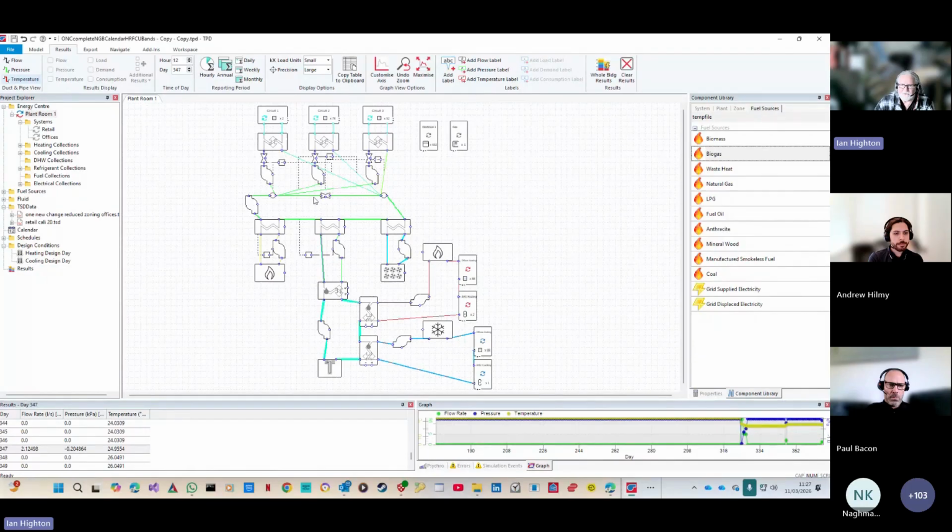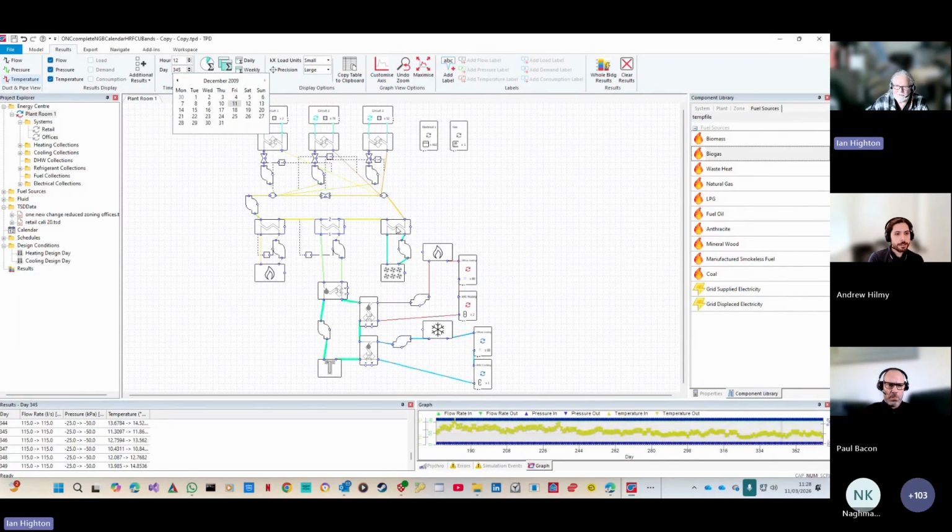So this is just a water circuit that just goes round and round, and obviously these heat pumps then pull heat or reject heat into that loop, and that loop, so that's the retail circuit, has to acquire heat or lose heat, and it's got 3 ways to do that. So these are heat exchangers again, this one and this one, and these are dry air coolers.